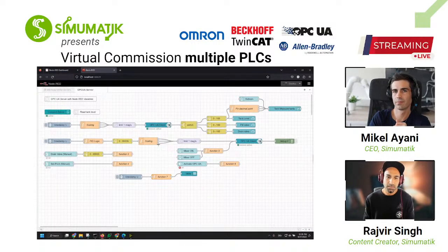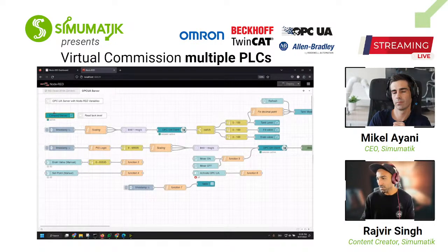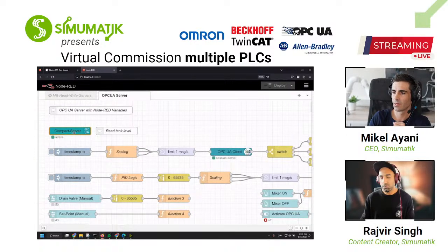Cool. Normally, in the last videos, I was connecting to an OPC server in a specific PLC like Siemens or CODESYS, but Node-RED is completely free. And you can use a node called compact server, this one, and this has all the variables which you can define inside.